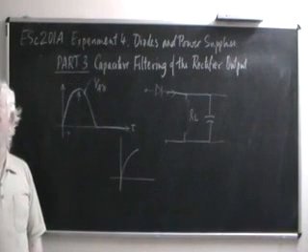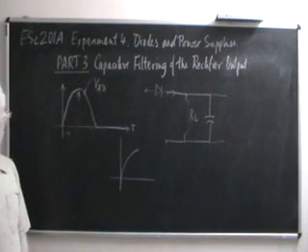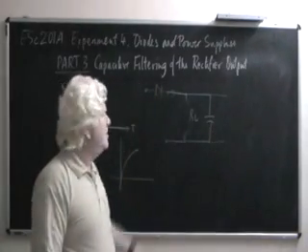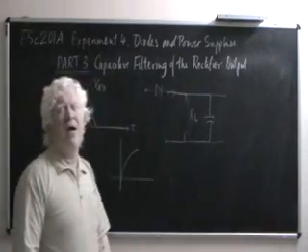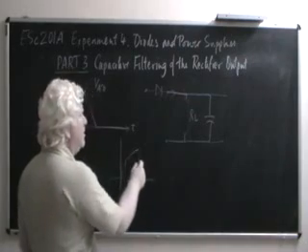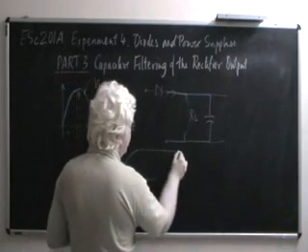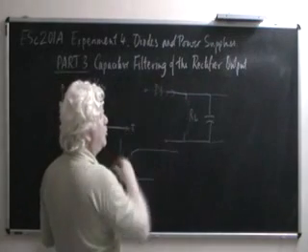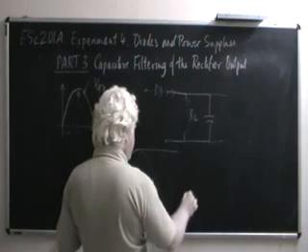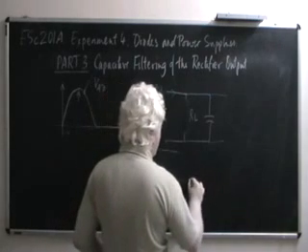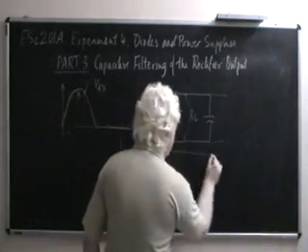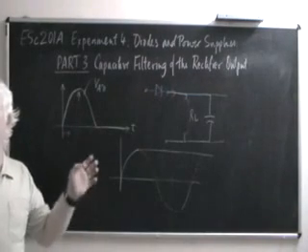And after that, the diode does not conduct. The output, under ideal conditions, when there is no resistor and when the diode's reverse resistance is infinity, would follow this up to this point and then would remain flat. Whereas the input to the rectifier has gone down, gone negative, gone up again, gone positive again. This just remains flat forever and ever under ideal conditions.